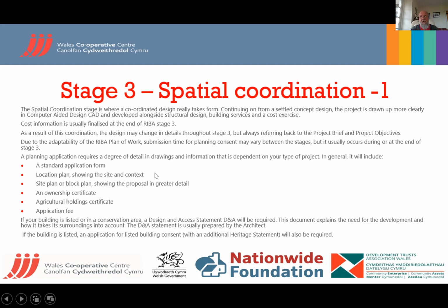The site and the context. You need a block plan showing it in greater detail and effect and proximity to neighbours and footpaths and highways. You need to have an ownership certificate to prove that you own the land. Do you own any other land next to it? It could be that you own one building and you own a plot of land next to it and you're developing that. So both those would be in on it.